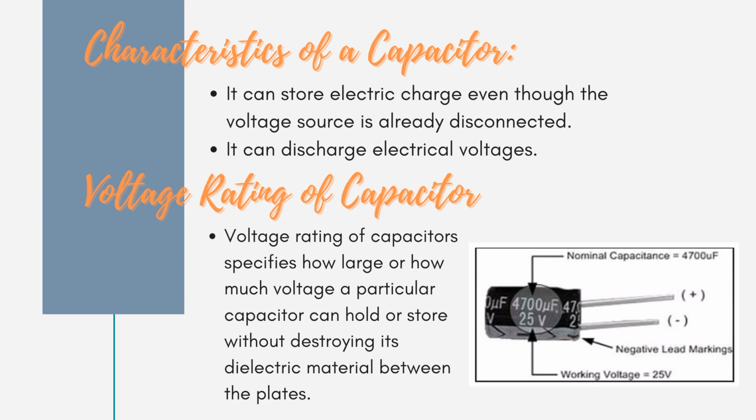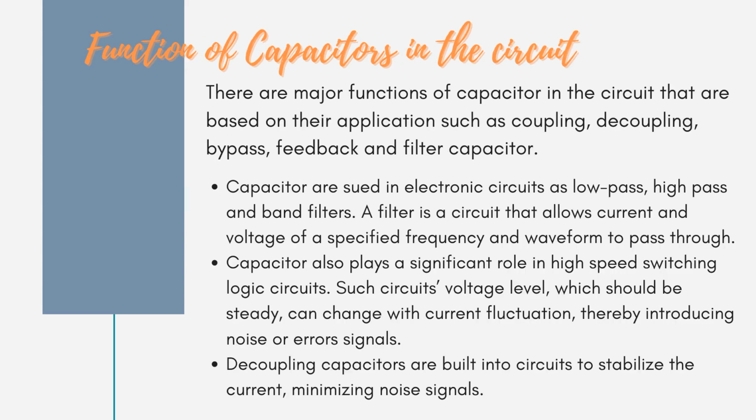Voltage rating of capacitor. The voltage rating of a capacitor specifies how much voltage a particular capacitor can hold or store without destroying the dielectric material between the plates. Function of capacitors in the circuit. There are major functions of a capacitor in the circuit that are based on their applications, such as coupling, decoupling, bypass, feedback, and filter.